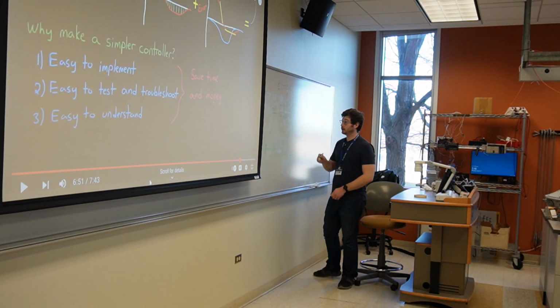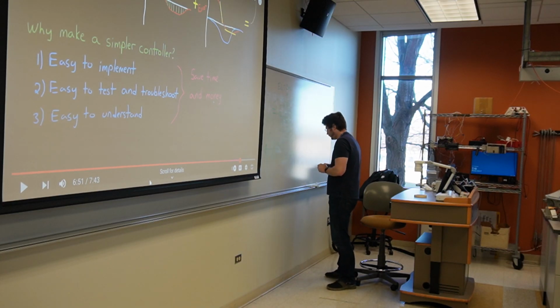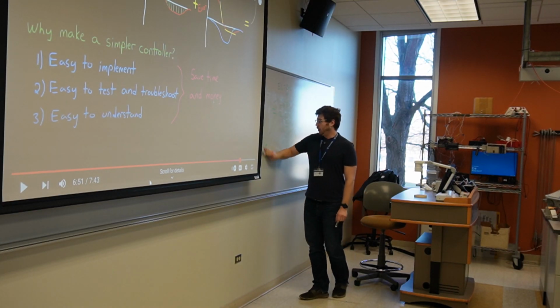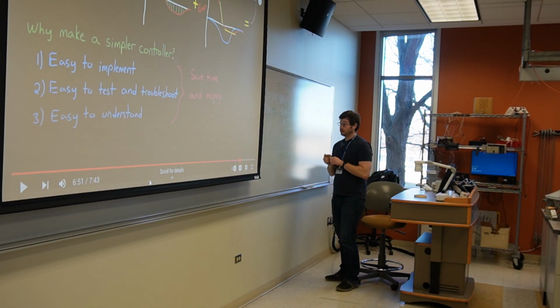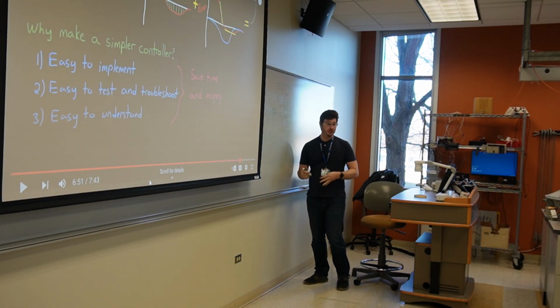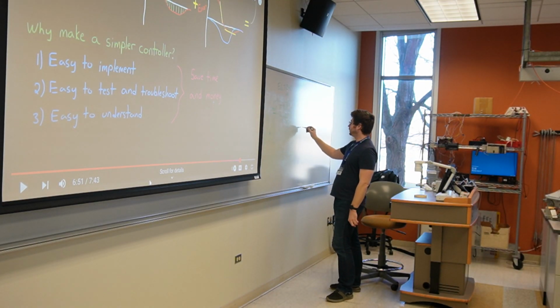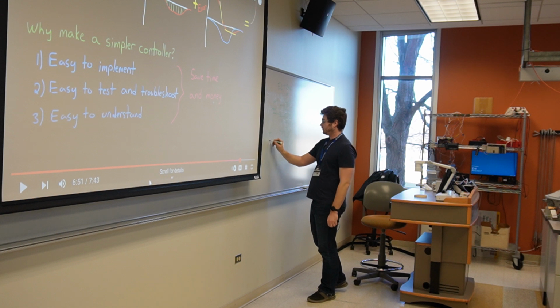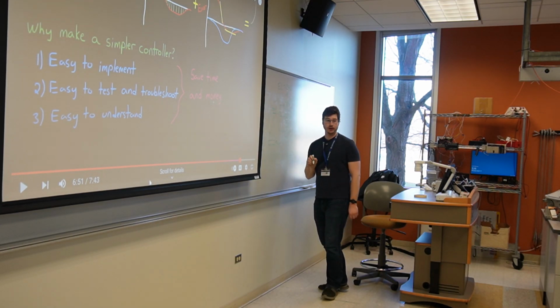This is where our integral controller comes in. The integral brain really doesn't like being off for long periods of time. It gets progressively more mad. In our speed controller situation, if we want to be at 45 miles an hour, but we're at 44, we're just a little bit off.